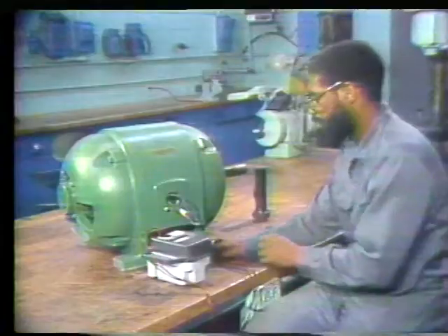Let's say you've looked at the motor over carefully, but you didn't find any sign of the trouble. You know there's something wrong with the motor because it isn't operating right. Maybe it won't run at all. Well, you know that you're going to have to test to find out what's wrong with it. But where's the best place to start? Well, most problems in three-phase motors occur in the stators, so that's the best place to begin your testing. There are three common types of faults to look for in the stator of a motor: grounds, opens, and shorts.